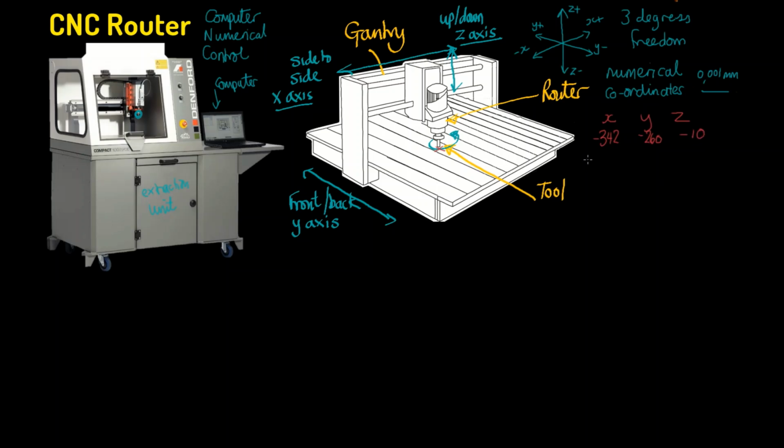Now in the programming, we also need codes. So we have things like G codes, which are proprietary codes, which really means about the tool direction and the tool movement. So if you're doing, say, a curve, for example, it's whether you're going to go in the clockwise direction or the anti-clockwise direction. So we have G codes like G02 and G03 that will determine that.